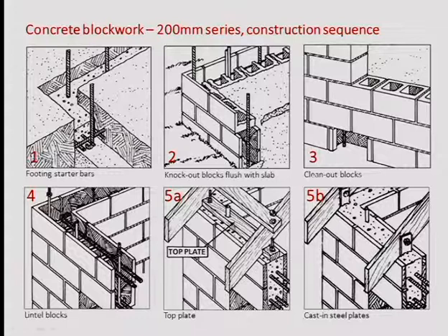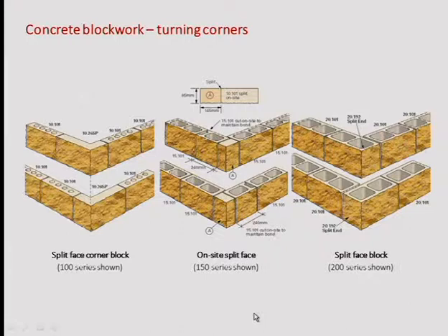And you see some details here, that there are some reinforcement rods already embedded in the strip footings. And then you place the concrete blocks. You have some L-shaped elements here at the corners. You have some clean-out blocks here to be able to assist the reinforcement rods. Generally, there is a coupling nut, so they are connected together through a nut. You don't need welding. Lintel blocks are generally reinforced so that they can carry more load. You see, this is suspended cantilever, and you can pour concrete in it, so this is a lintel block.